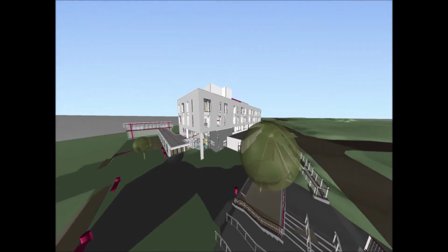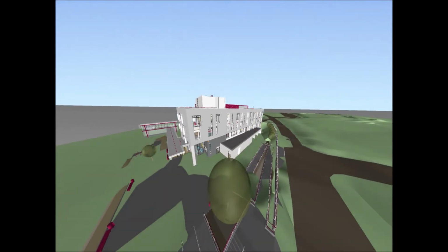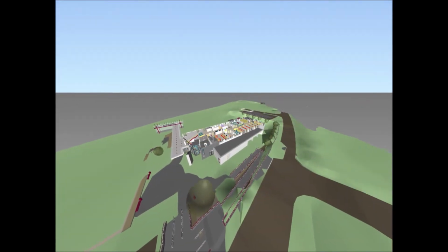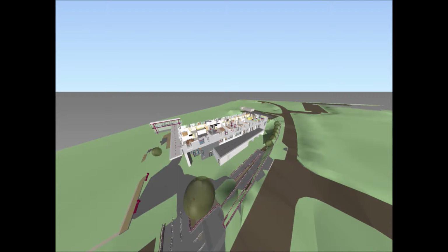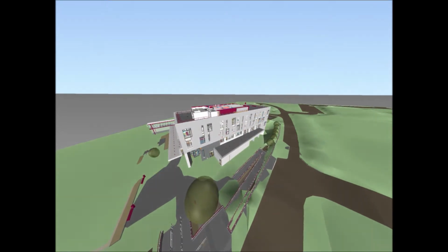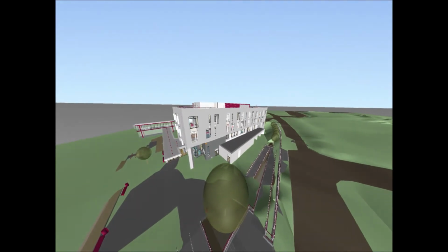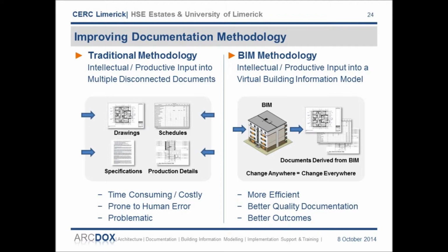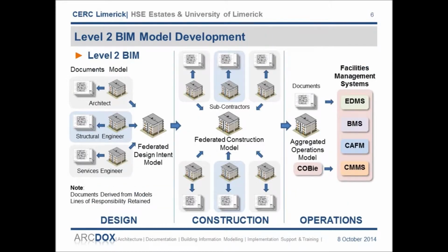What the contractor and subcontractor are required to do is set out in detail in the BIM protocol, the specification, the Employer's Information Requirements or EIR, and the BIM execution plan, the BEP. But in short, rather than producing traditional submittal, shop and fabrication information in a 2D process, we are asking everyone to produce their information using a 3D BIM methodology and to bring these models together for review and coordination with the other elements before executing the work on site, so that issues can be resolved as early as possible and risk and unnecessary costs can be avoided.